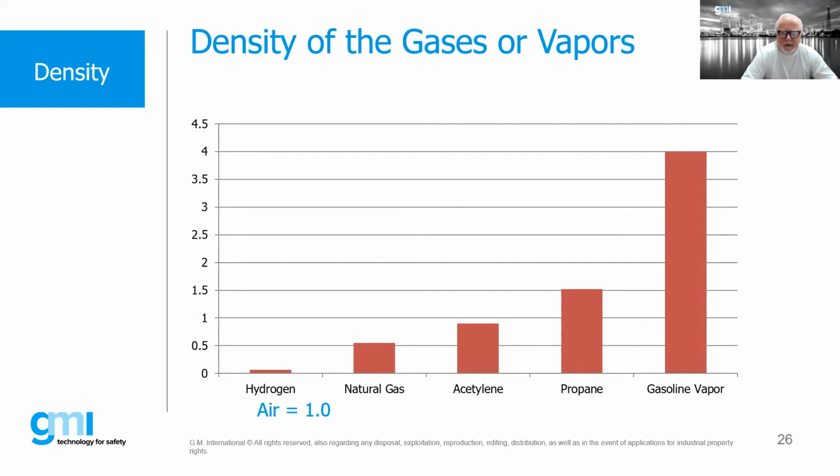Inside of the pump unit itself, there's some EX equipment, but the lights right above you, because gasoline vapors are heavier than air, as soon as they start rising in any way, shape, or form, get dissipated by the air. Therefore, we don't have to have EX lighting at a gas station. On the other hand, if we have hydrogen inside of a room, hydrogen being lighter than air is all going to go up near the ceiling.